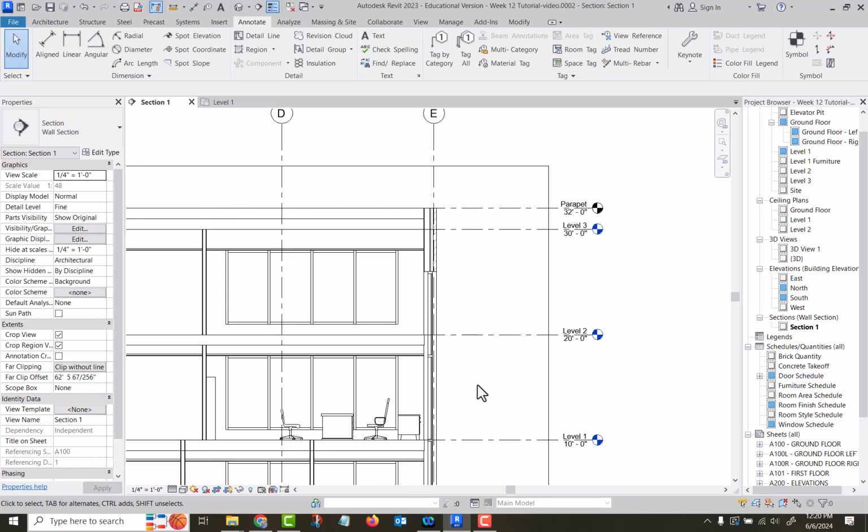And there's a couple of different ways of doing it. You have to have a keynote library file. One is using the CSI designations of the materials, and another is just a 1, 2, 3, 4, 5, 6 kind of a thing. But you have to have a keynote library set up, and that would be something that your BIM manager would do, or if you're in a small office, you could set it up with some experience.